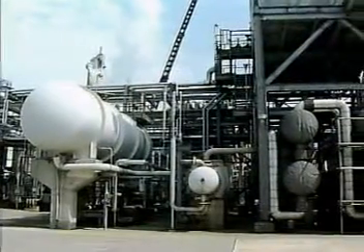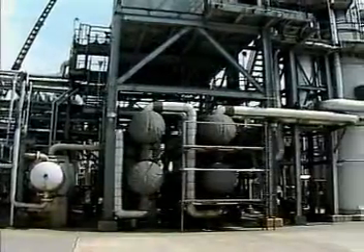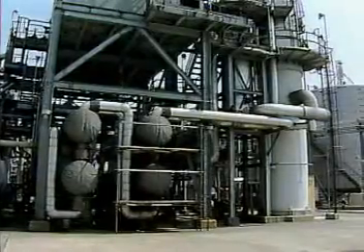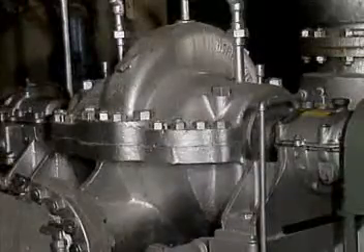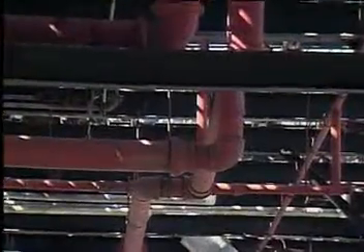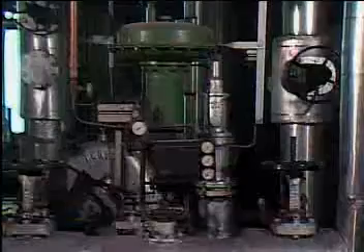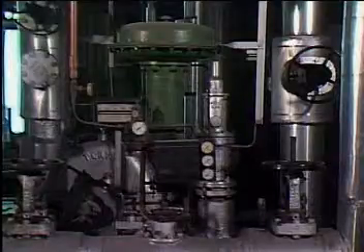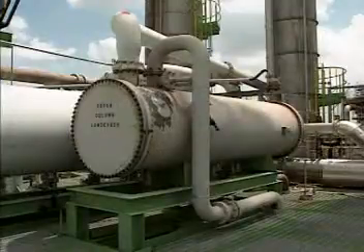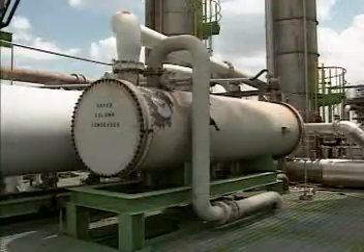A fluid system is made up of components that function together to perform a specific task. To accomplish its task, a system must have at least 4 basic parts to satisfy certain key requirements. For example, a system must have an energy source to provide the energy necessary to carry out the task, a transmission path to transport the energy or process medium from one place to another, one or more control devices to adjust or change operating conditions in the system, and one or more components that carry out the specific task of the system, and in doing so, create a demand or load on the system.